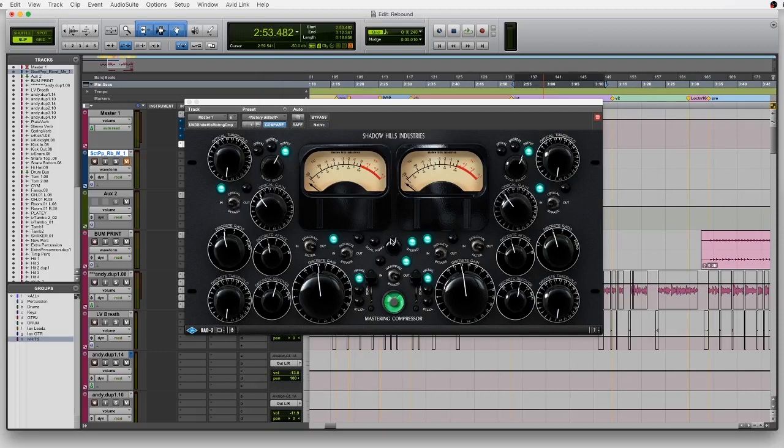The central knob allows you to choose whether your input material will be processed in stereo or dual mono. In stereo mode, any signal breaching the threshold, whether it is from the left or right channel, will attenuate both left and right equally. In this mode, it is only necessary to adjust the controls on the left.